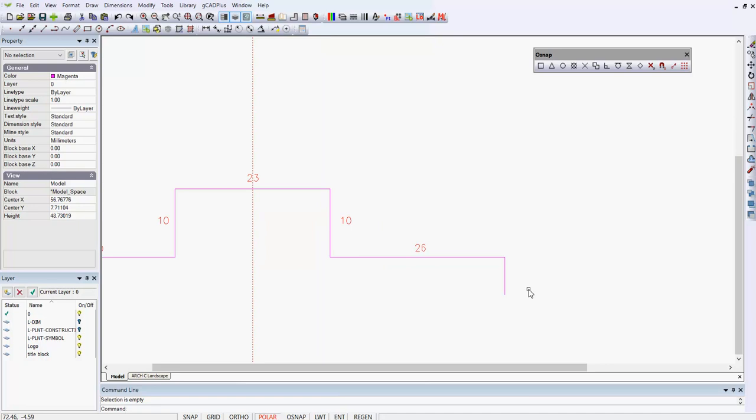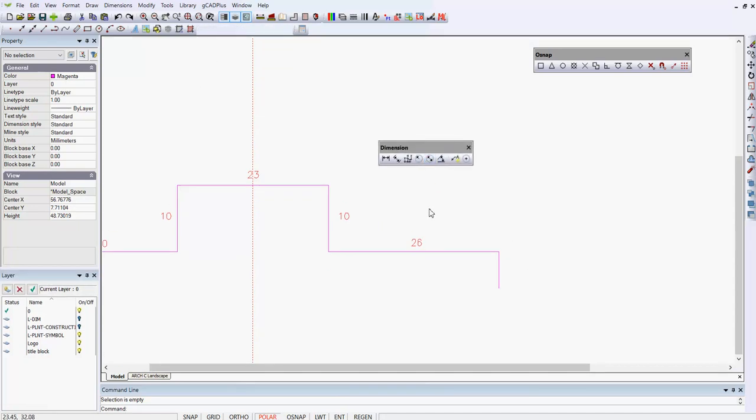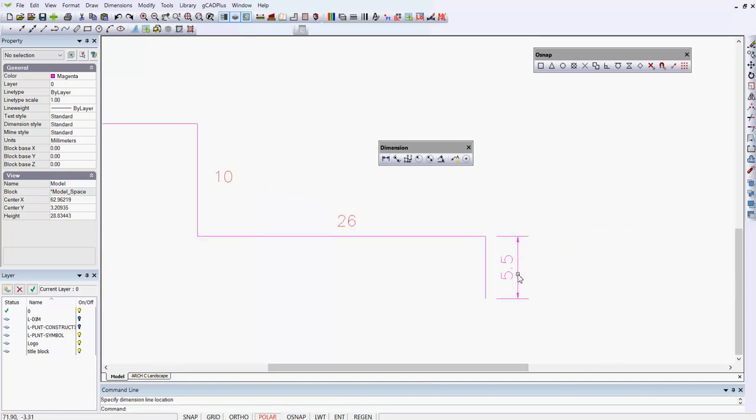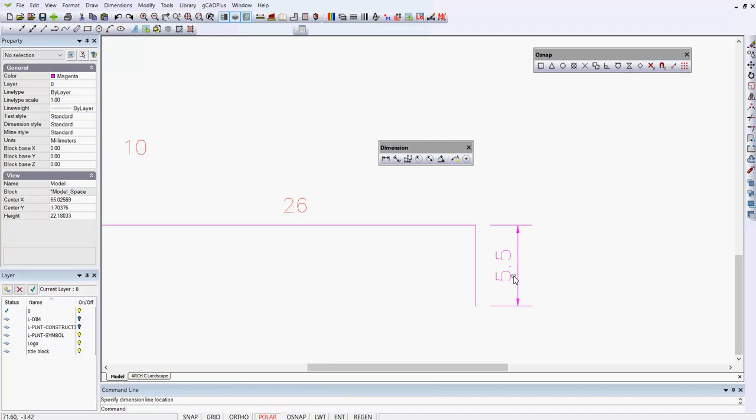Dimensions are taken from the model. So there's a dimension toolbar here. Let me float it over here. If I wanted to measure and put an indicator on there of how long that is, I could pick this linear dimension. I can make the cursor jump or snap to the end point and snap to the end point again, and it should say 5.5, and it does. And the dimension is drawn in whatever colour is set as the current colour. So I hope that shows you how to put the footprint of the house down. It takes a lot longer to describe than it does to do.